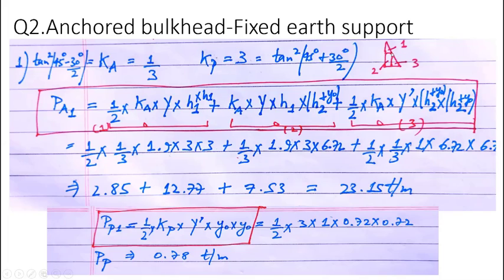So at the water table, this is the pressure distribution, triangular. Then this continues downward to the bottom layer up to the depth of this, H1, this is H2 plus Y0, because this is the point of contraflexure. So this calculation is the area of the triangular diagram, rectangular and another triangular.